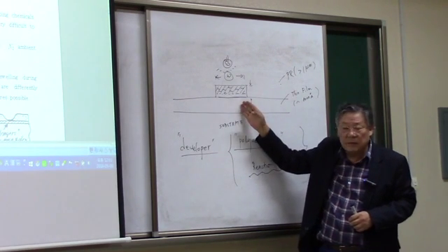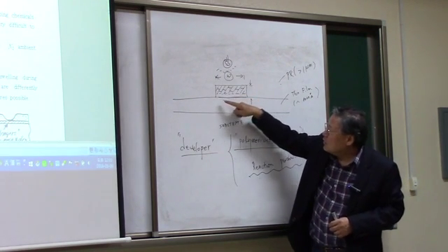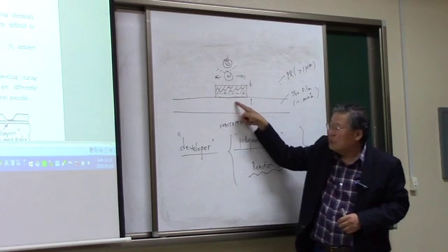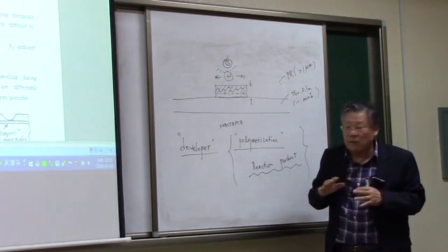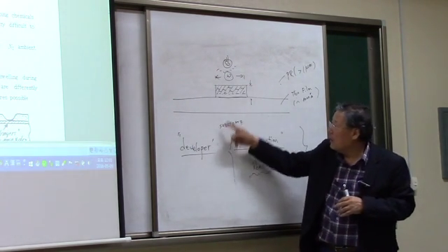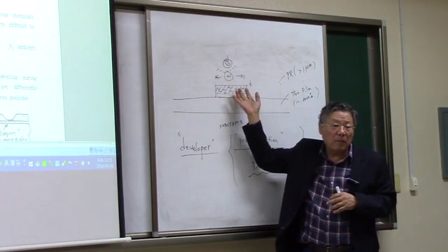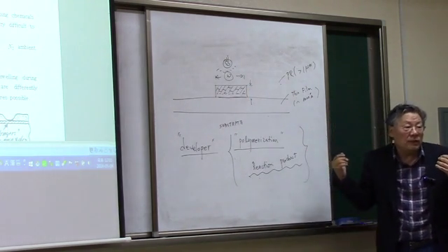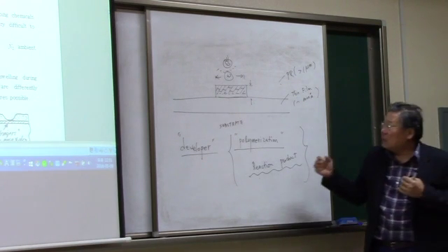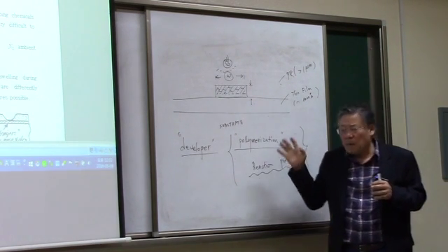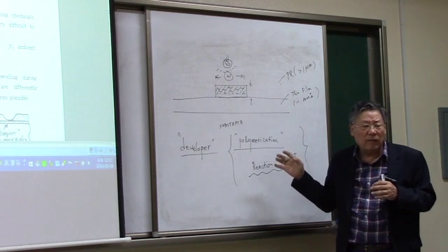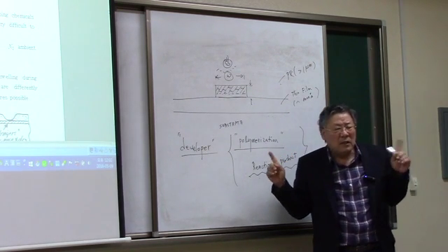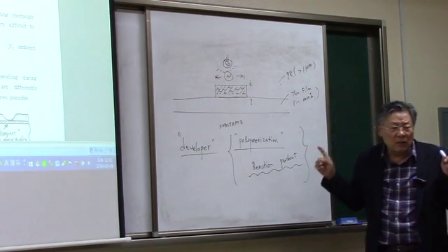If this happens, then the adhesion of this negative photoresist to the substrate is not good enough, so that during the developing, the photoresist is going to fall off from the surface. So that is the main disadvantage of the negative photoresist.